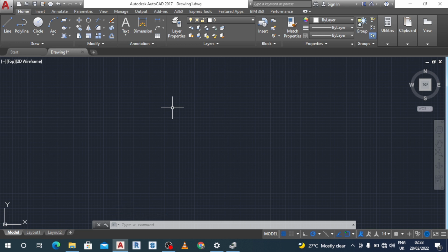So we've taken lines, we've taken erase. The next thing I'll be teaching us now is construction line. Construction line is very important. Please pay good attention. This construction line is basically what I use to start up my construction. Whenever I want to draw a building line, I start with construction line. Our construction line can be found underneath our line tools. You'll see a tab like draw.